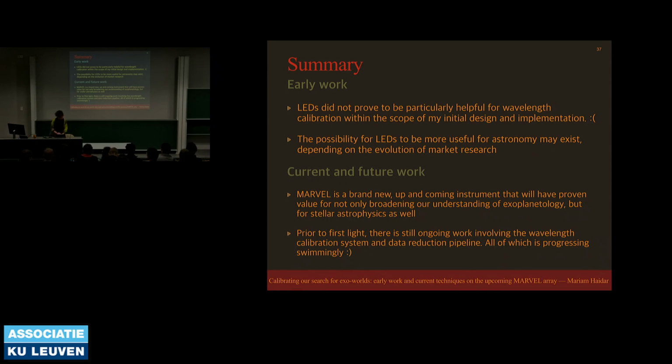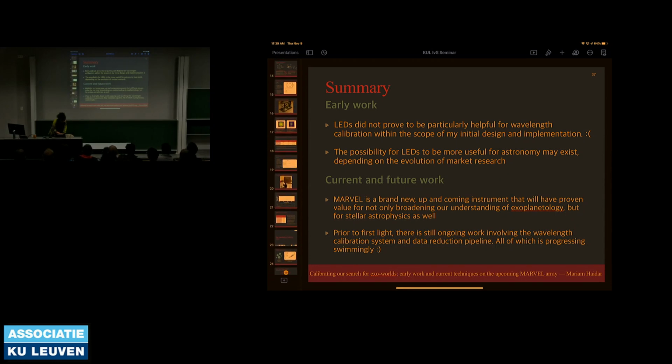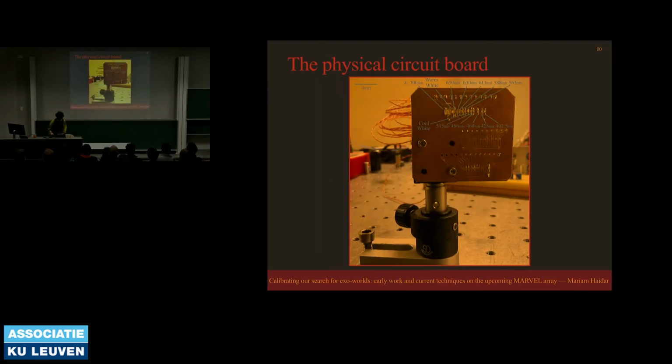Yeah, so white LEDs exist, and they were actually part of my second design. I have a warm white LED here and then a cool white LED over here. So white LEDs appear white to the human eye based on two different styles of mechanisms. One is using RGB, so the white light will have a combination of a peak in the red, the green, and the blue. And then another style is that it will peak in the blue, but it will have like a phosphor coating on top of the LED, and the coating will absorb the light and then re-emit at redder wavelengths. And so that's how they appear white to us.